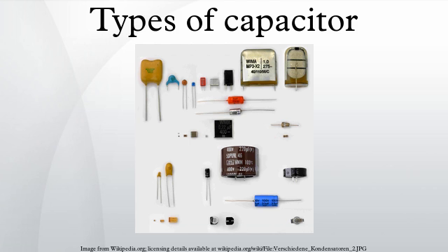Double-layer capacitors were named for the physical phenomenon of the Helmholtz double layer. Pseudocapacitors were named for their ability to store electric energy electrochemically with reversible Faradaic charge transfer. Hybrid capacitors combine double-layer and pseudocapacitors to increase power density. Silver mica, glass, silicon, air gap and vacuum capacitors are named for their dielectric. Capacitors in each family have similar physical design features, but vary, for example, in the form of the terminals.